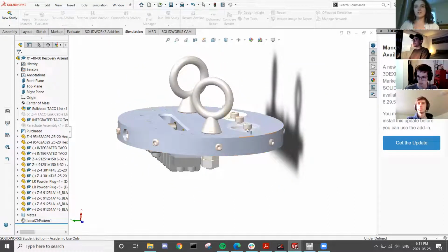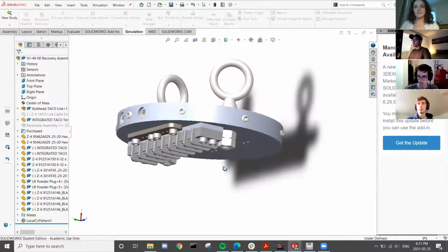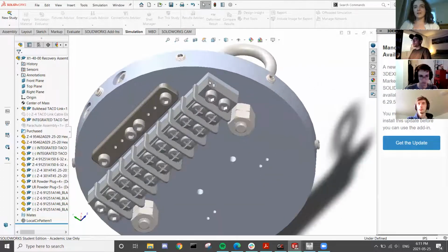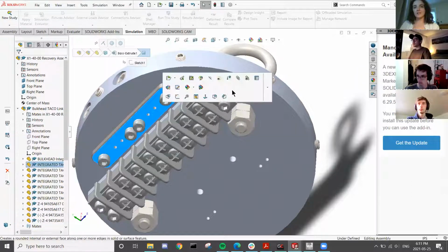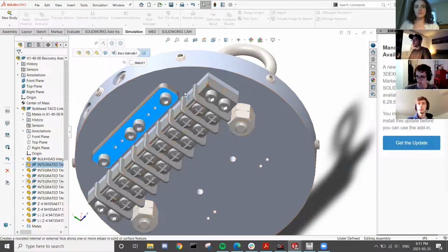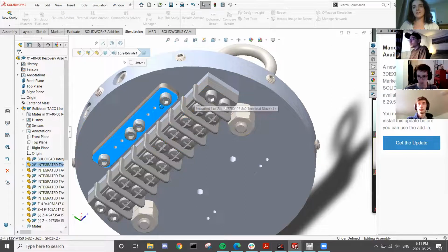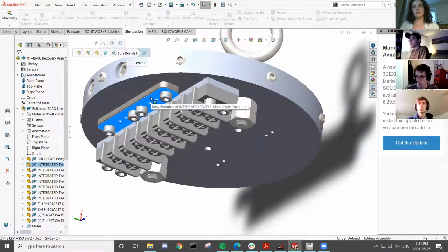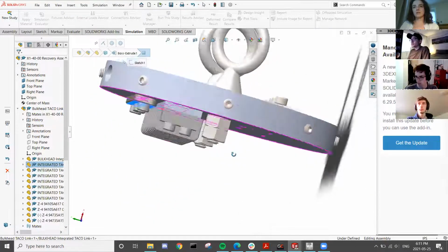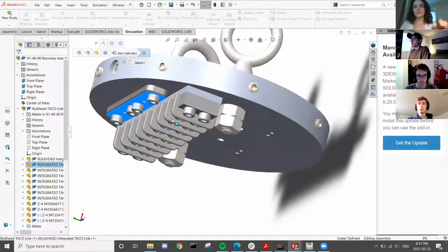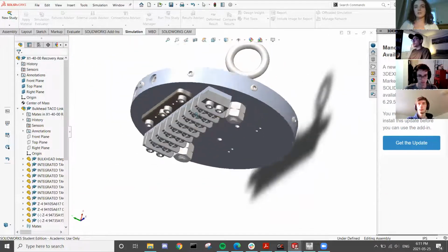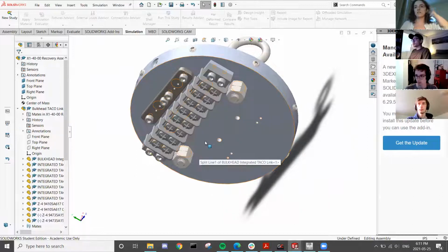So these CO2 covers and fasteners, I also deleted. And I got rid of these guys, all these blocks on the back, basically because ANSYS, or like the free version of ANSYS, can't handle too many faces, and there shouldn't really be too much load on them compared to the bulkhead, and they're steel, so they're stronger. And when you start getting too many connections, your simulation gets kind of bogged down and can be less